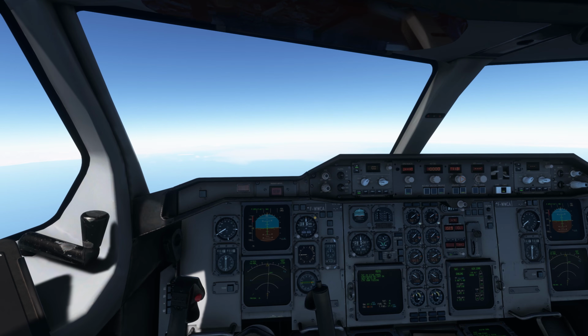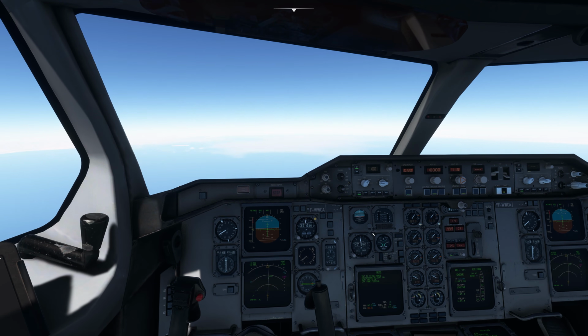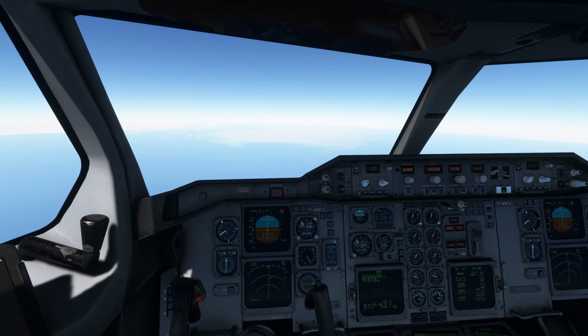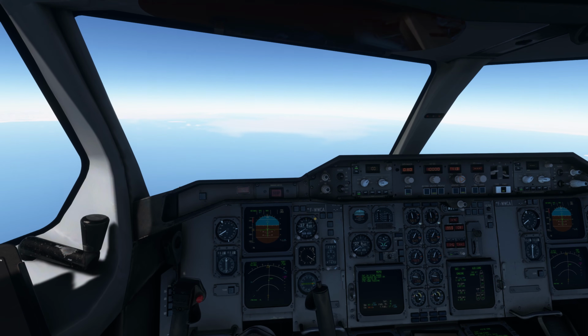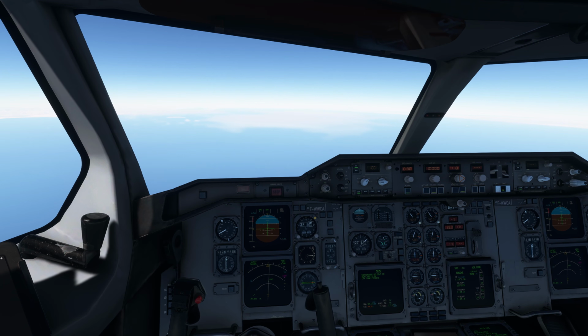So it didn't start. What I can do is this. I can press this button, level change, and then the plane will start to descend. Now you can see the vertical deviation is coming. This is happening to me for the second time. This is the second recording that I'm doing. First I did the RNAV approach, and now this is for the ILS approach. Every time I start recording, it doesn't start to descend automatically in the profile mode. But when I'm not recording, it happens.